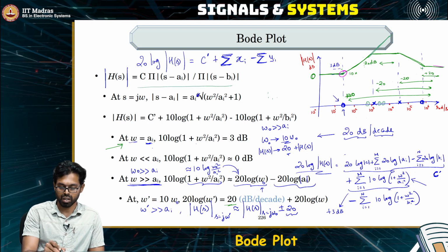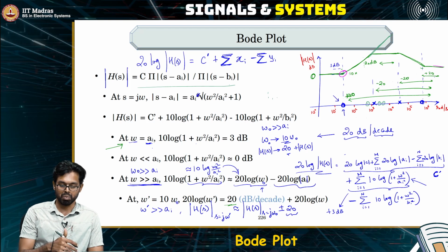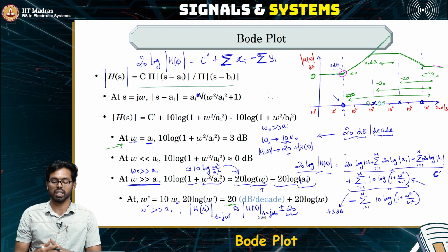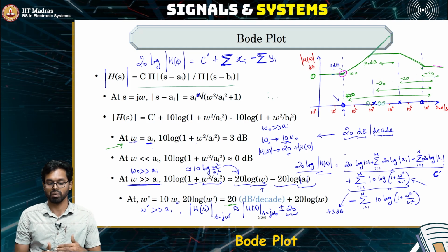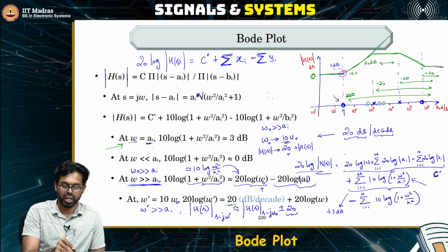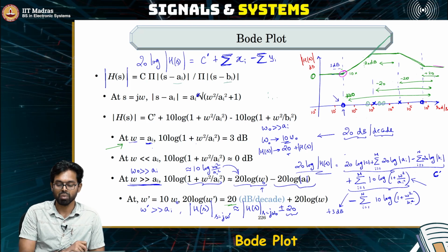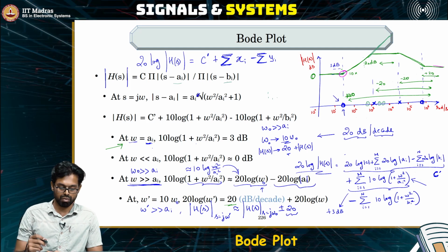So once you construct a transfer function back from that, you will know what would be the impulse response. All you have to do now is try and construct a system, try and find what should be the resistor values, capacitor values, and what should be the inductor values, such that you get a pole and a 0 in these locations. So that would be the design problem that we can solve.